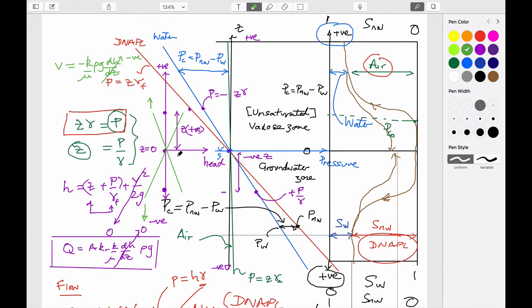But it's important to be able to make the distinction between pressures and heads. So pressures vary linearly if they're static, as controlled by the unit weights of the fluids, whether the fluids are very light or more dense. It's directly proportional to those. But the magnitude of this gradient of fluid pressure, if you convert the fluid pressures to a head, just using this simple expression that we have here, then that gives you some information exactly about where those out of balance fluids, what they would do in terms of driving flow.